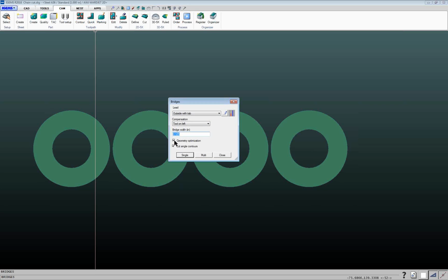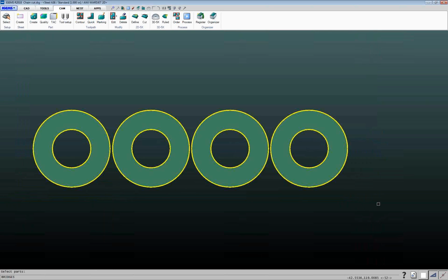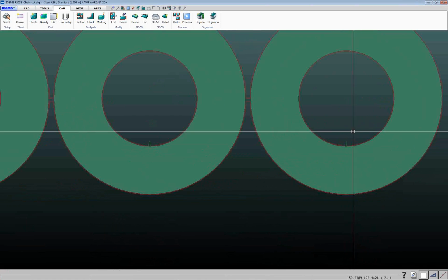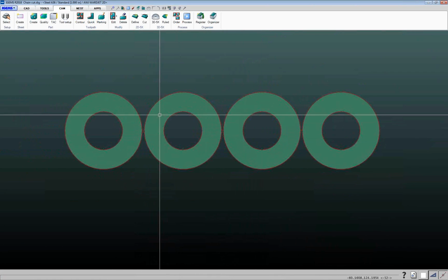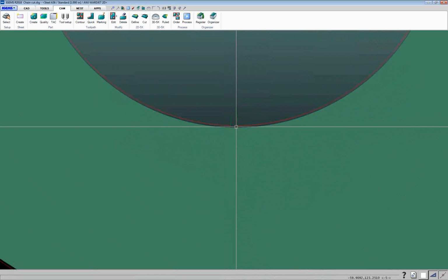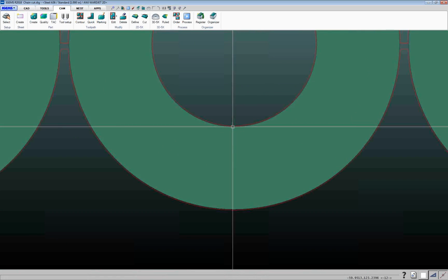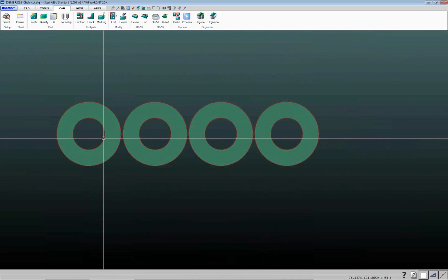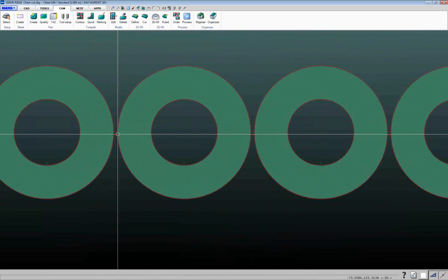Geometry optimization will figure out how far it can get into a tight geometry, and then if you want it to add tool path to these IDs. So if we just do it right now, click on multi, select these parts, hit enter, and click on close. It puts my tool path on all my inside cuts, and because I told it to use the outside lead with tab, these have the tab on there also. That's a situation where you might prefer not to have put the toolpath in there using that single option, but we'll come back to that.